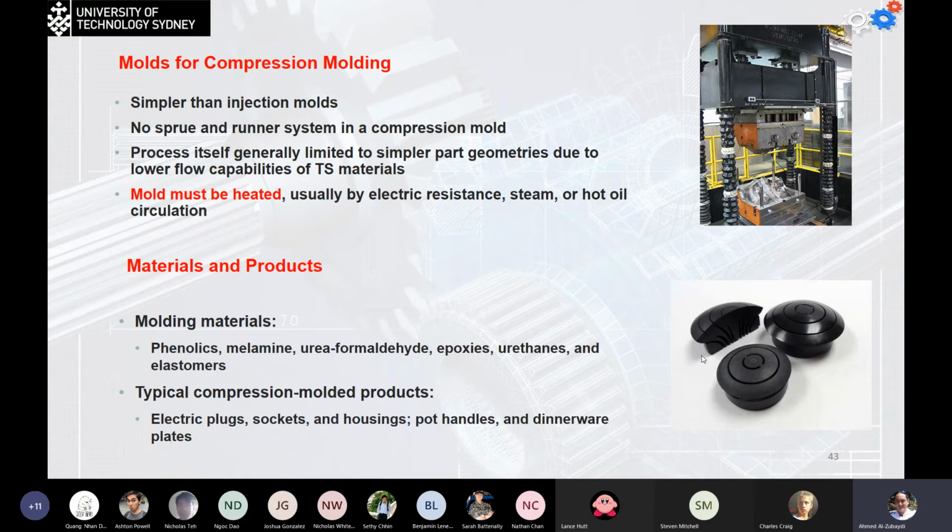Have you ever thought about that this plastic has been made from a different material, because we use it at higher temperature, but it never melts? And also you can check something. If this part is going to be broken, you cannot use, for example, super glue to weld them, because super glue is only used for the thermoplastic, never used for the thermoset material.